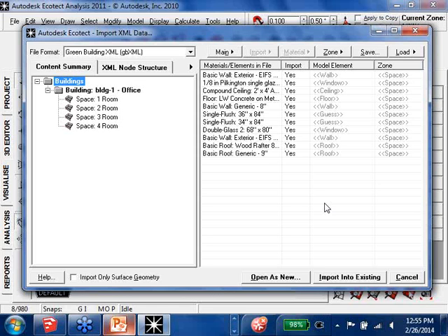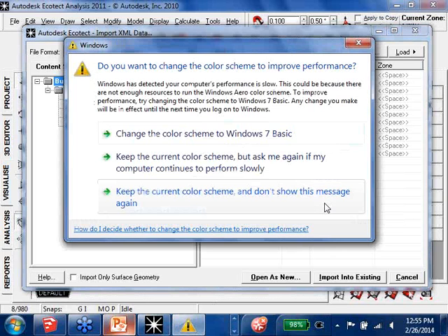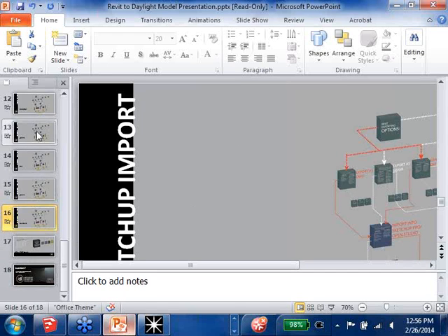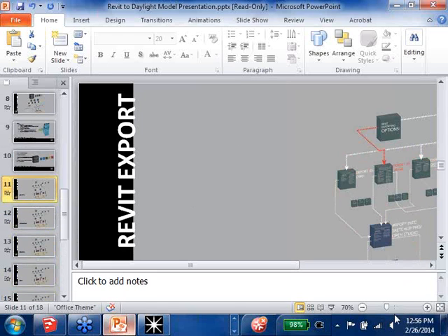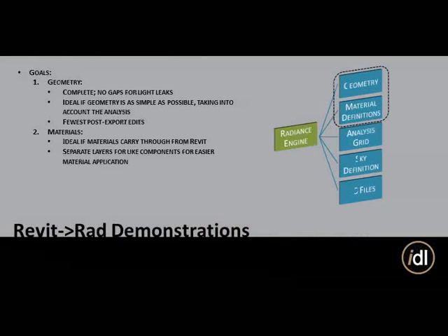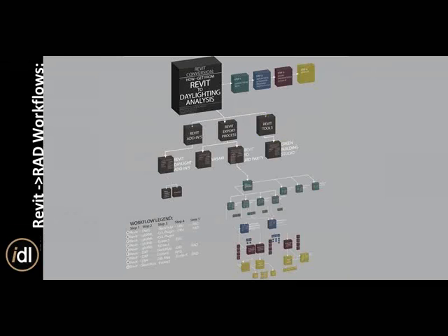If you go through any of these more complex pathways, we've been showing how to get into Radiance analysis, and that is the industry's most accurate program because of the way that it does daylight calculations. So I would say that it is probably the most accurate and most flexible output that you can get, although it's really dependent upon the appropriateness of the analysis, right? If you're doing LEED daylight analysis, you might not want to go all the way down to Radiance. You might stop at OpenStudio, or you might stop at regular Ecotect.